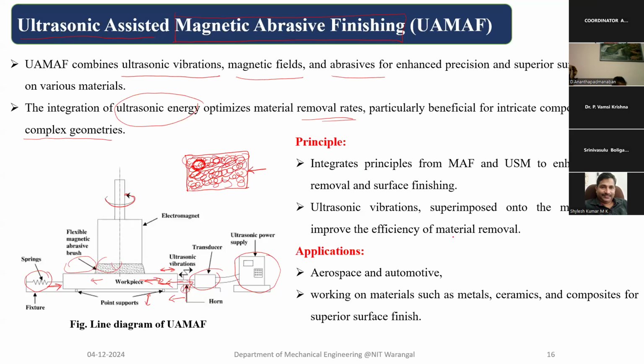The principle is integration of MAF, which we discussed already, with ultrasonic machining: the ultrasonic vibrations are superimposed onto the magnetic field, and the material is removed in a better manner. Applications are in the aerospace and automobile industries, working on metals, ceramics or composites for super finishing. This is a little improvement on the magnetic abrasive finishing process.